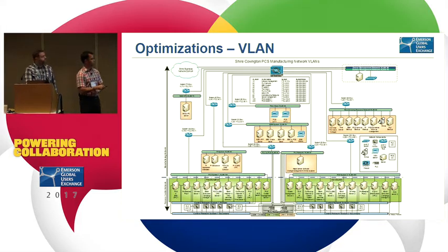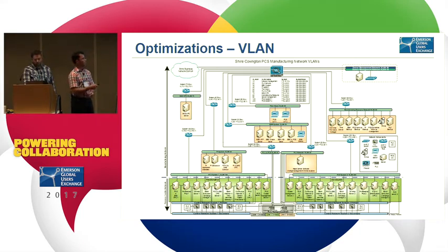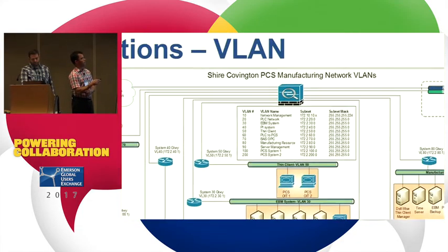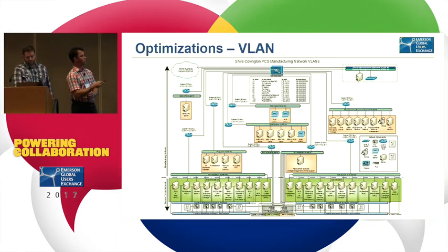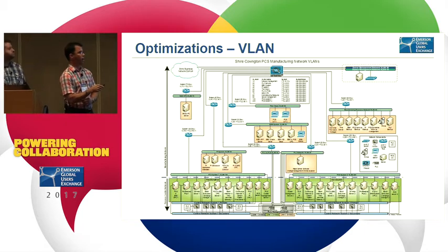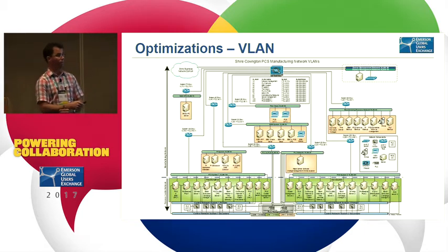Let's say we have the PCS system 1 VLAN, with a range of IP addresses, a subnet, assigned to it. When data needs to go from the PCS system to our MES system, it is the firewall/router that takes data from VLAN X and transports it to VLAN Y. That's not handled by the switch, it's handled directly by the firewall, which also has router capabilities.